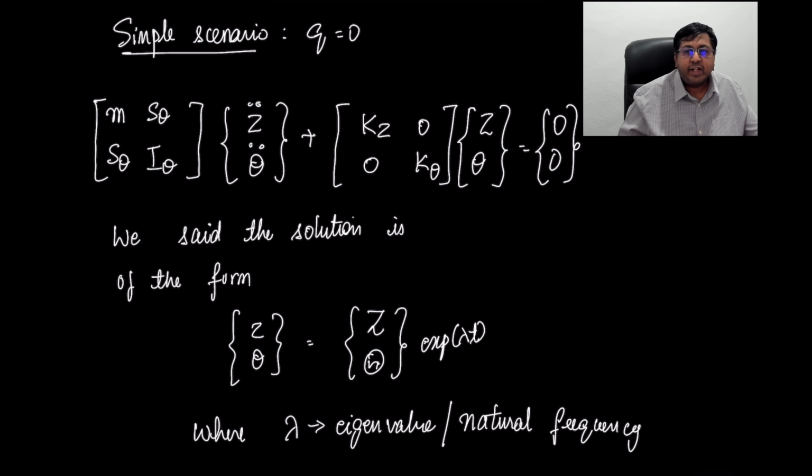If the stiffness matrix was full and there was a coupling from the stiffness matrix, it would be called stiffness coupling. In other words, the coupling essentially means that each of these motions, the heaving and the pitching, are affecting each other. So far we assumed a very simple idea: what would happen if the damping matrix goes to zero, or the airflow velocity itself is zero, like a static situation, and how the pitching and the heaving motion change because of that.